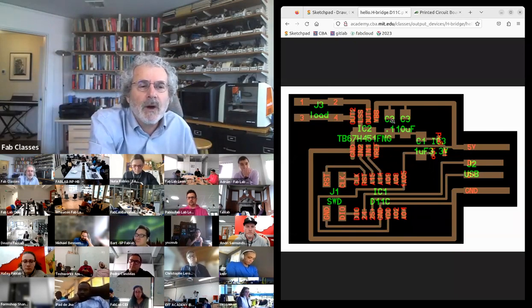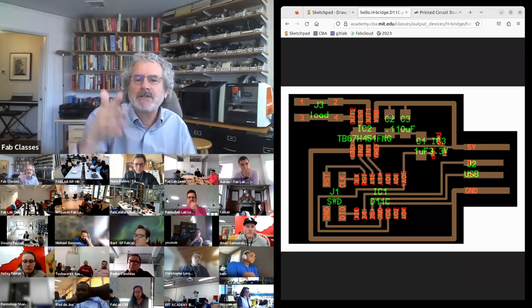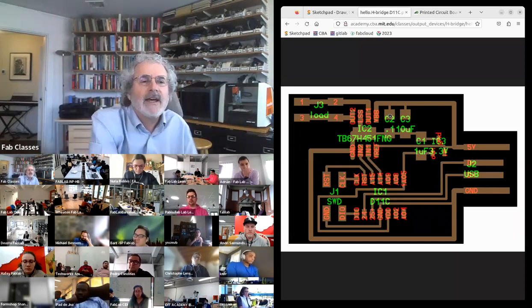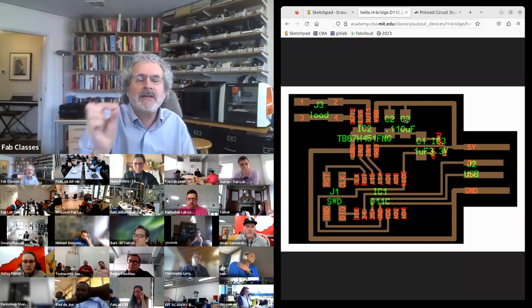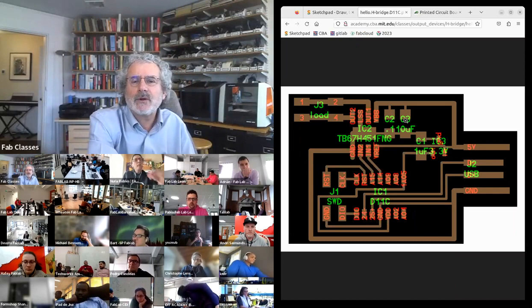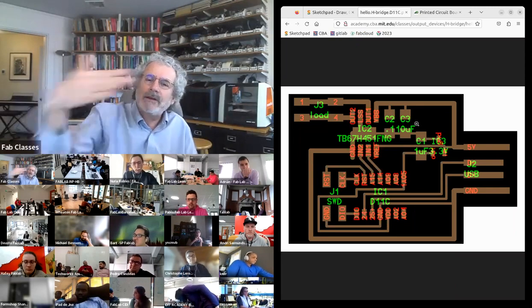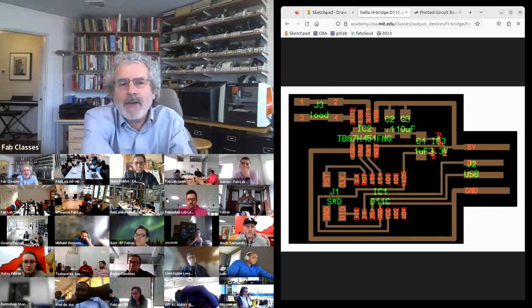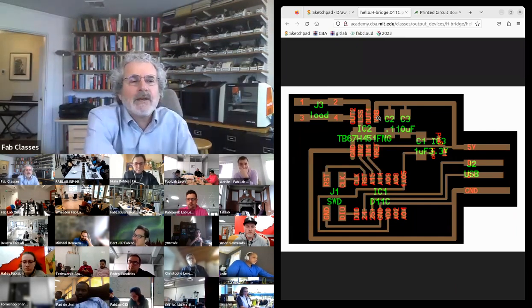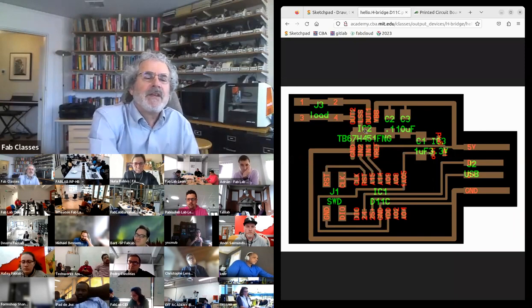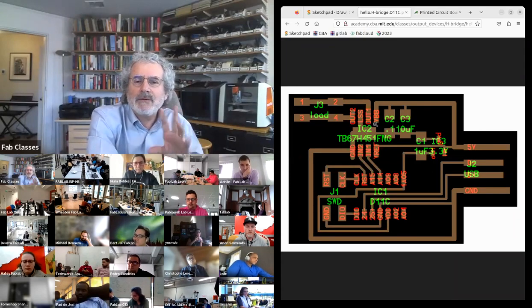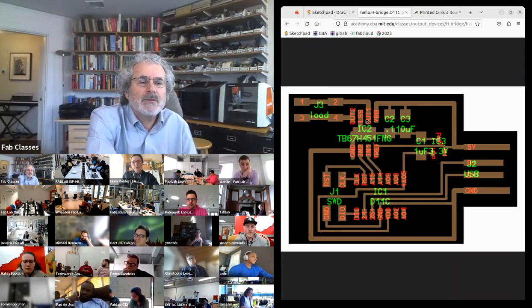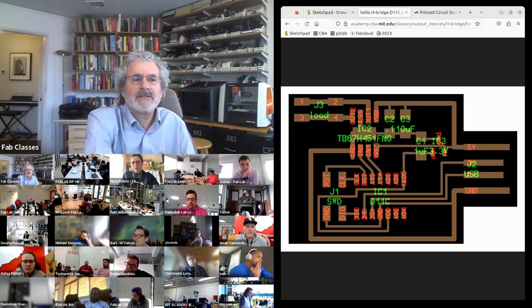And so the smaller capacitor acts like a filter to try to filter the glitch. And the bigger capacitor gives me a little bit of extra local power storage until more current comes in from the supply. And so I'm adding extra bypass capacitors around this. If you don't do that, you can get really subtle bugs where, like, when this switches, it actually makes the processor itself reset.